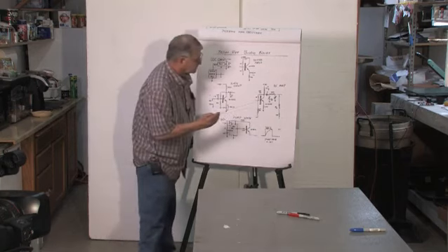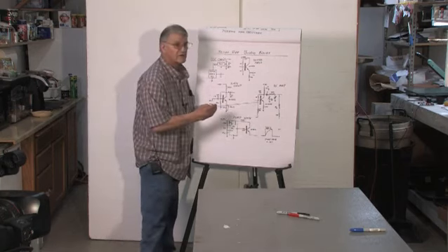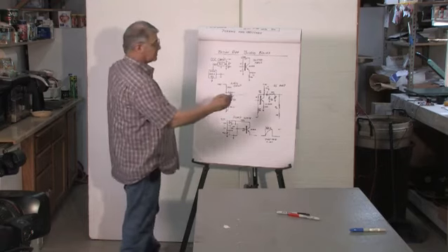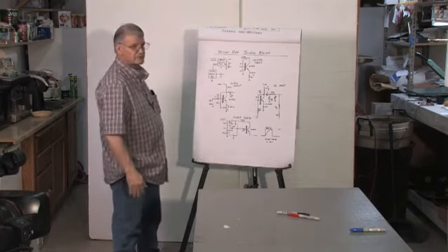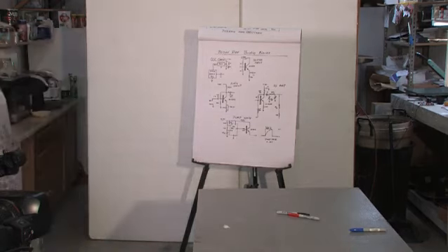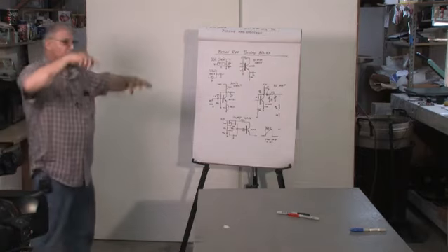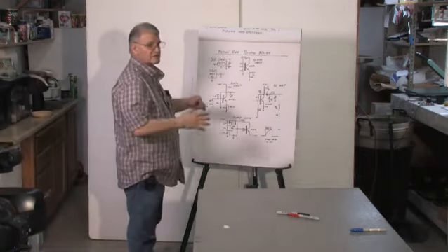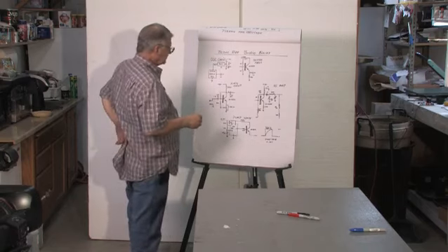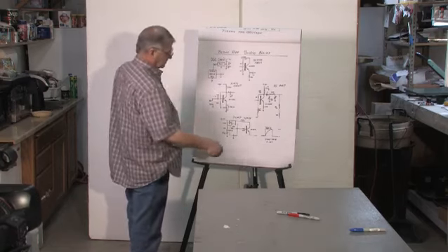And so what's happening is the audio is gating this RF transistor off and on to produce the sidebands. It's actually distorting the wave, which if you were to watch it, it wouldn't look perfect. It would be distorted. So that's the basic functioning of the whole circuit.